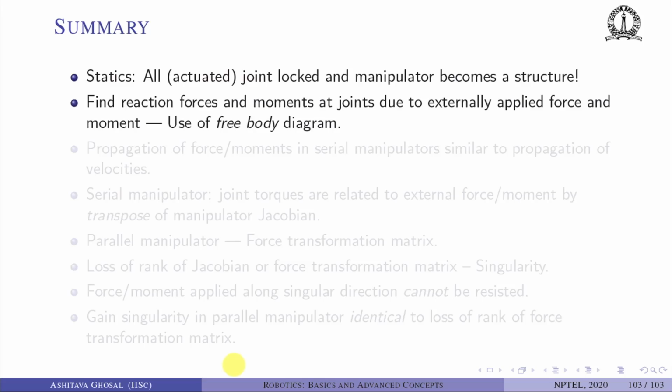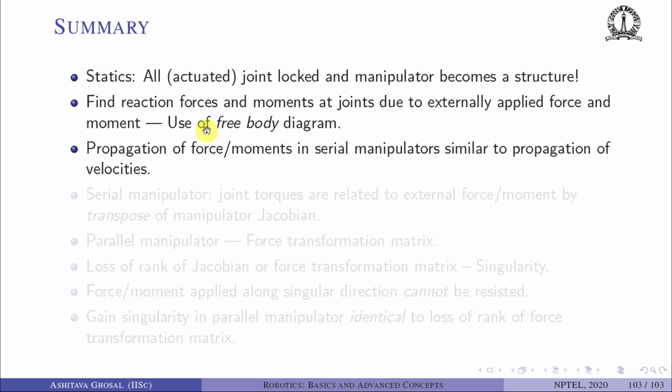So in summary, statics. When we look at statics, all the actuated joints are locked and the manipulator becomes a structure. So we can find the reaction forces and moments at the joints due to externally applied force and moment using free body diagrams. Okay, propagation of forces and moments in serial manipulator is similar to propagation of velocities.